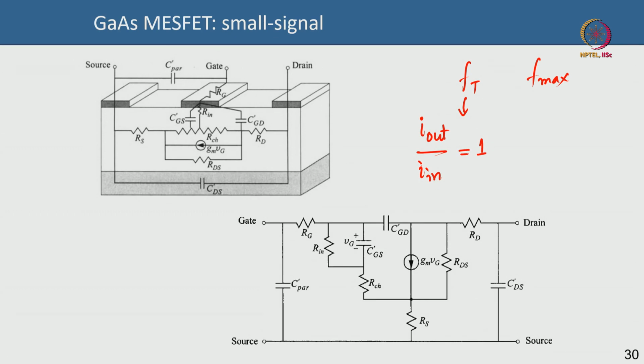So, of course, like many of the things that you have studied in your undergrad electronics, if you plot your gain on a semi-log scale against frequency, you will have the gain fall with frequency. Okay. And there is a 20 dB per decade slope after hitting a pole, but the gain will fall with frequency, and this is true for any system. In the case of a transistor at higher frequencies, your carriers are not able to cope up as much. So, physically the intuition is that the higher the frequency you go, the electrons that are moving are not able to deliver you as much gain.